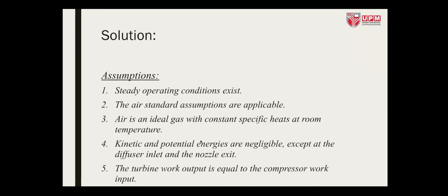Even though it's not being asked for you to write down the assumptions, these are the kind of assumptions that we can treat for this particular problem: steady operation, air standard assumption, air as an ideal gas, kinetic and potential energy are negligible, and the turbine work output is equal to the compressor input.